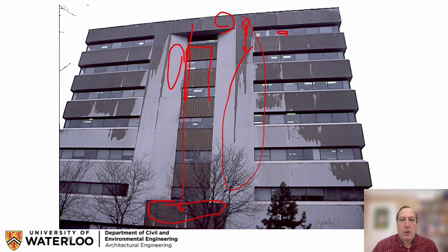But also importantly, the window sills, which you can see better in these lower buildings, are just a steep slope that takes the water and dumps it onto these panels. And you can see the joints are not having as much water, and that's likely from the shape of the joint. But when you look really closely, it will be something that redirects water to certain directions.